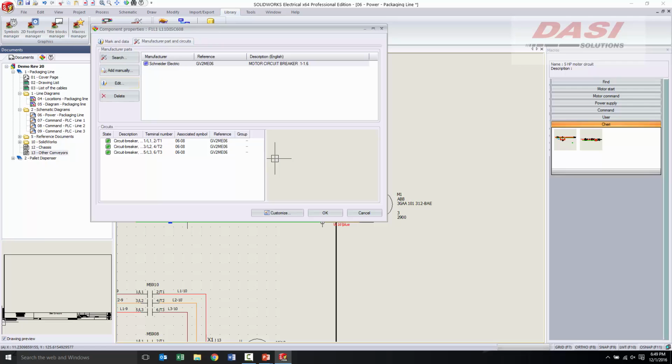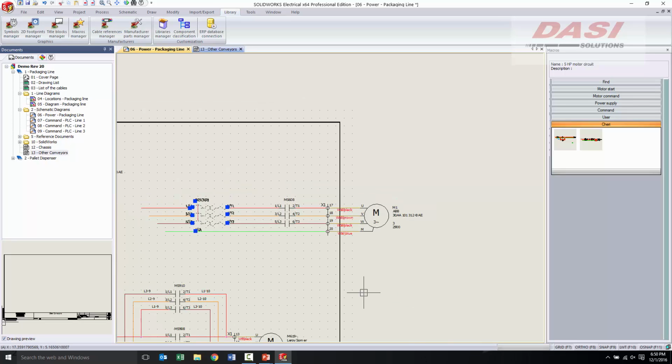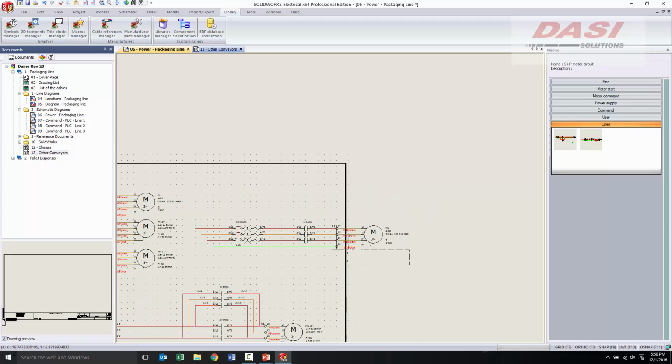What you have to be really careful with too is, and this is where Mrs. Clark really kind of messed me up, Mrs. Clark only had one main panel, right? So we didn't have a JB2, and we terminated the motors directly into that main, we didn't have a JB1. So with that, I had to be careful with not using that as a full macro, so to say, because let's say I put it into a standard filler, then I would drop that in, and all those would be just the main cabinet. Right. There would be no separation.